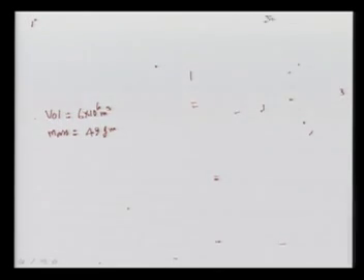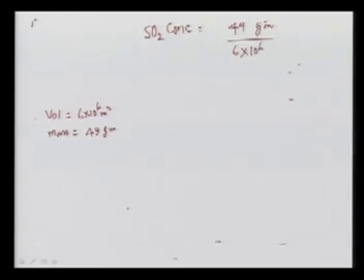How do we find the overall concentration? Well, mass divided by the volume in which it is dispersed. That will give me the concentration of SO2 in the region. So, fair enough, the SO2 concentration is this: mass is 49 grams, 49 gram divided by 6 into 10 to the power 6 meter cube.